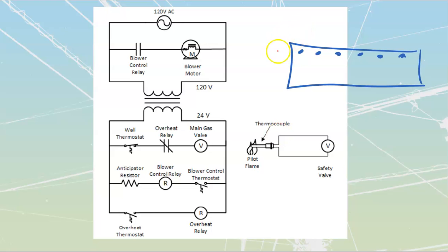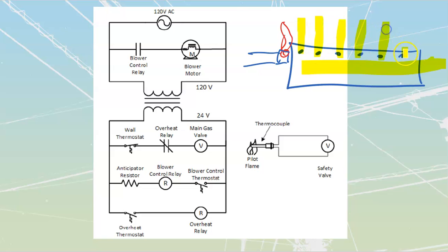And then what you'll have is a pilot light that is just going to be lit and sitting right here down by the end of it. So something is going to be continuously lit and running over at this end. It's like having a lit match that's sitting there waiting. That lit match is waiting until we turn on the gas flow into this duct. Once we turn on the gas flow into this duct, it's going to fill up with gas, and gas is going to start coming out of each of these individual little jets.